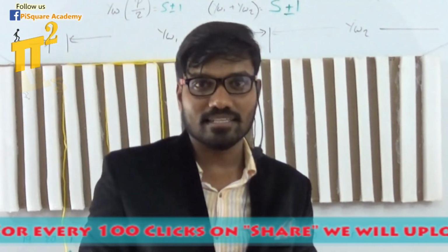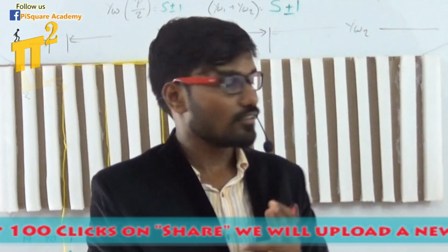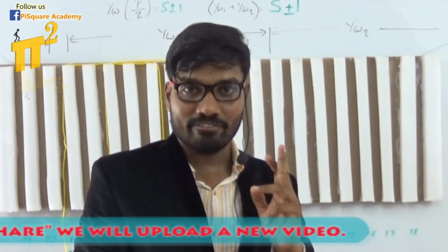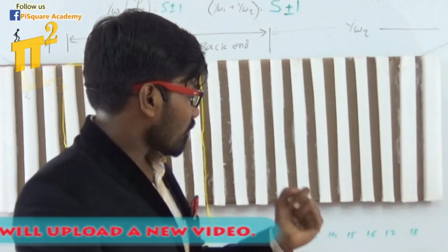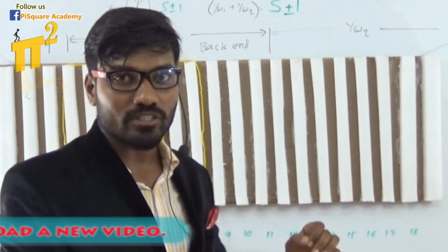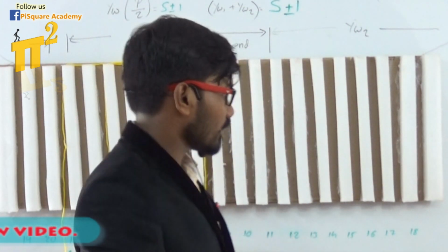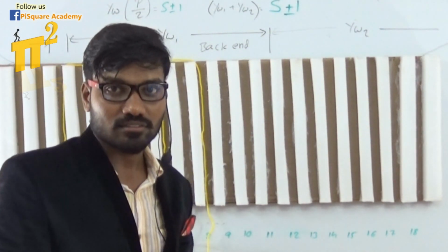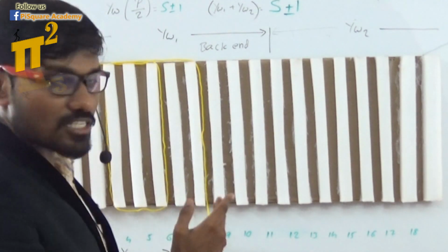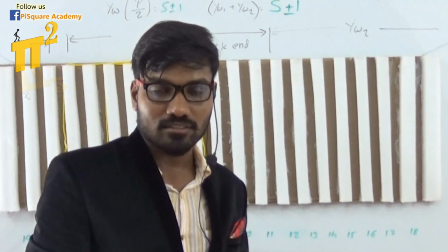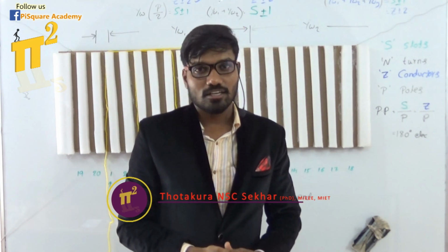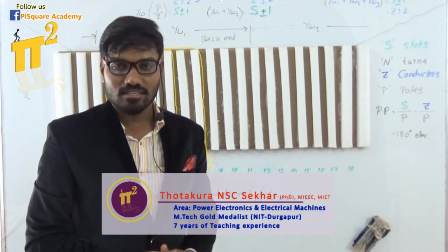I hope now these things are clear. What is the first one? Number of conductors is always an even integer. Number of commutator segments is equal to number of coils. Okay. And back pitch and front pitch are always integers. Alright. Progressive winding, retrogressive winding, that is clear. Simplex, duplex, and singly re-entrant, doubly re-entrant. So now one thing is left, that is double layer winding.